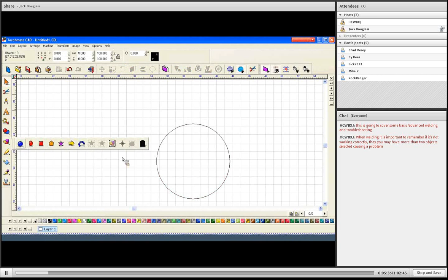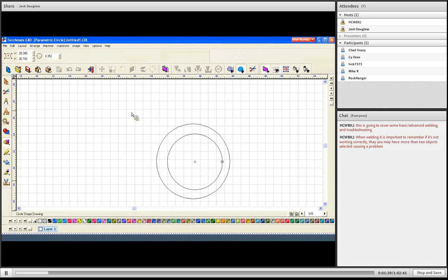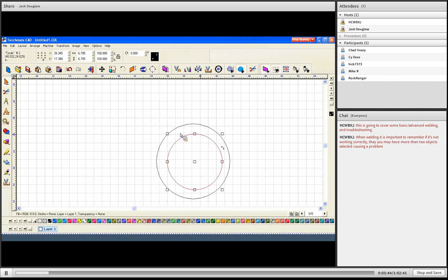We'll then make another circle for the inside. And we said that there was going to be a 2-inch border around there. So in that case, this would be 5 inches. And actually, it looks like maybe it was 1.5 inches, but for our circle, we'll have that. Now, I've also locked this, so in the future, if I change one of these, it will change the other. So if we went to, say, 6, then we'd have 1.5 inches around the whole thing once they're centered up.